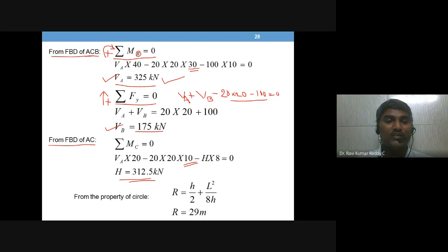So take another free body diagram, of either of the portions from the hinge, to the left of the hinge, which means the crown, or to the right. Draw a free body diagram and use the sum of all moments either to the left or to the right of the section taken.